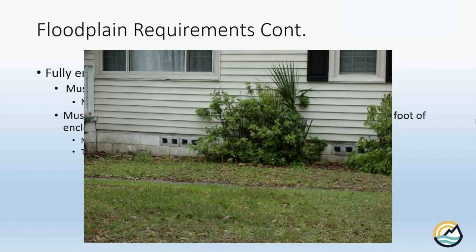That's fine. So when people tell me I can't afford flood vents, I like to tell them, yeah, you can. You're already buying the blocks. Just turn them on their side. So something like that works. It doesn't have to be fancy. It doesn't have to be expensive. It just has to allow that water to equalize.